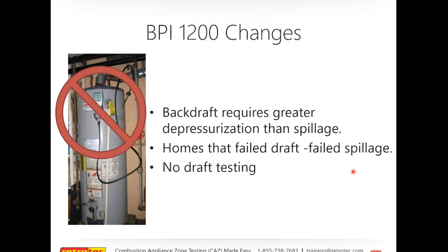Versus spillage. The word spillage actually means that it doesn't even really make it all the way into the flue pipe. I used to have a problem with this when I was first learning about it. I couldn't understand how some of that flue gas could begin to draft, but meanwhile it could actually spill out. And that's important to know too, because in this BPI 1200, we're no longer testing draft. Why did we in the first place, really? Again, that's my opinion.